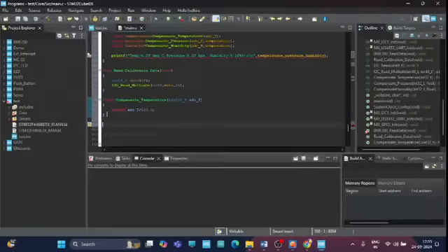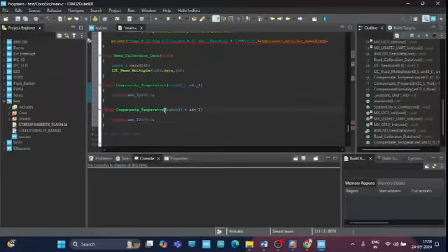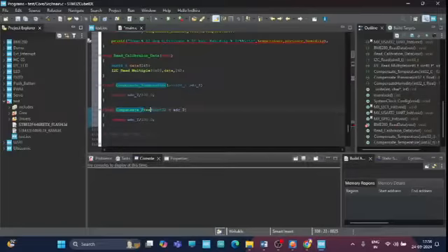We need to just, instead of temperature, use pressure. So unsigned integer 32_t ADC, this is for P, and then float temperature. Okay, and then inside, ADC P and 256. So this raw ADC value, which is ADC P, is divided by 256 to get the pressure.